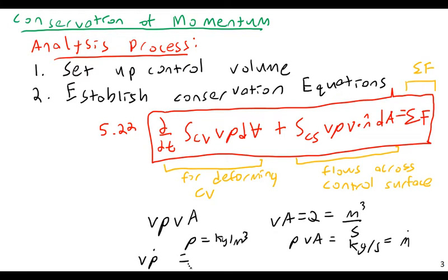If I'm trying to bring this back to basic high school physics, because it's a bit more understandable that way, this looks like, well, m dot is mass flow rate, kilograms per second. Sorry, that should be m dot. If I look at v m dot, that's kilograms per second times meters per second. So really what this comes to is kilogram meters per second, or momentum over time.